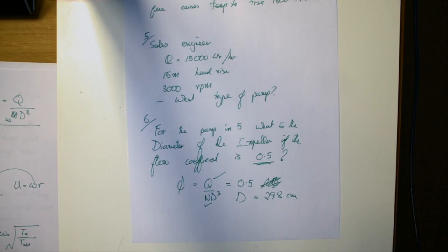And the customer sent a guy to come and check that the test was accurate, that the pumps really were doing what they were supposed to do. And what Mather and Platt was doing was cheating. Because the pumps actually didn't generate the head that was specified in the contract, they'd changed the setting on each of the gauges to show higher pressures than they were actually measuring. So we had a line of gauges. Now, the surveyor who had come to test that everything was all right came with his clipboard and his pen, and he carefully read all the gauges, and they were all showing the pressure rise that should be happening. So big tick, everything's all right.